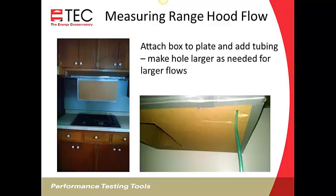If you're going to make a more permanent box, maybe you want to start out with a slightly larger hole. It'd be nice to have a slide on it like the exhaust fan flow meter, but I'm not sure how often you're going to see flows over 280. For kitchen fans, this will work much of the time. But if you've got a more permanent box, you may want to have a more permanent tap that you can connect your tubing to, instead of just having a hole you're pushing your tube through. Eventually that's going to become loose and your tube's going to fall out.